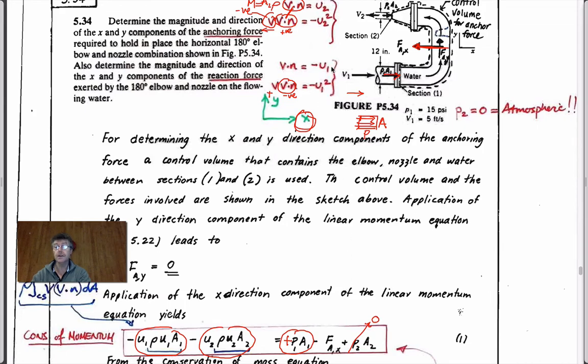Oh, because it's also assuming that the pressure acting here is acting in this direction like this and is P2. And it acts over some area A2, but actually it's atmospheric, and so we don't care. So if it's ever open to the atmosphere, it's basically pushing against it in. Well, it's assuming that there's some pressure that we could imagine here that's in this fluid. And if the fluid is outside the control volume, it has to be acting physically on this surface. And so it's acting no differently to the fluid pressure that's acting here, if it's positive.